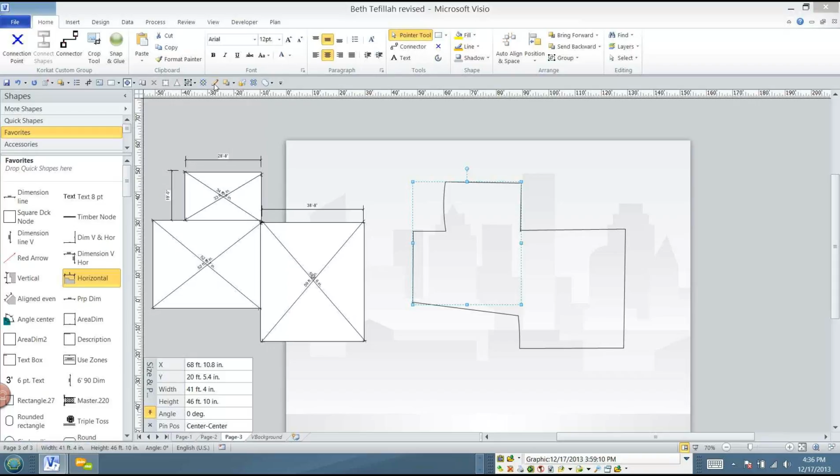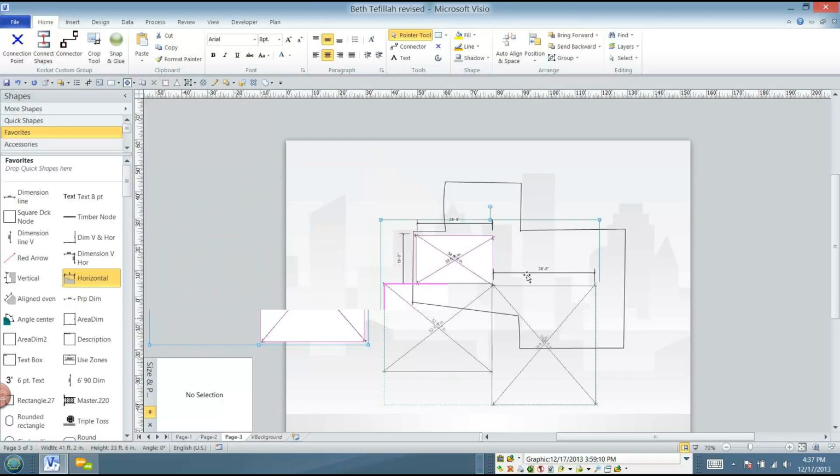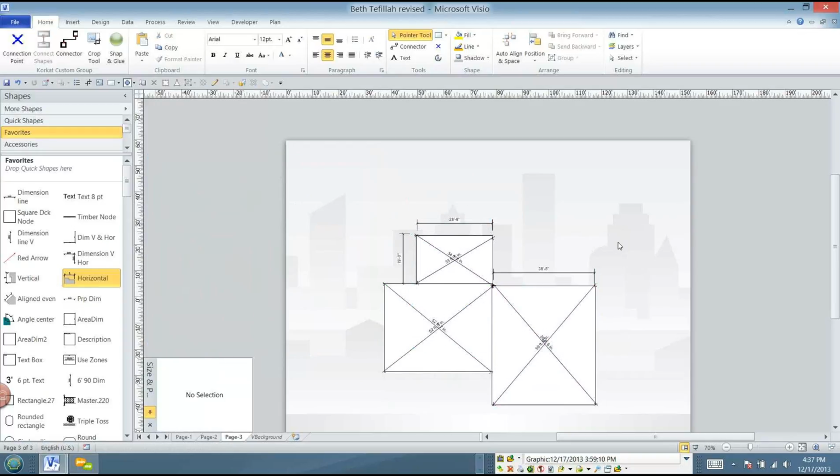This is in all likelihood what you would see. Be something similar to this. When you're walking out, taking your measurements, try to cut that up into usable pieces. Okay. So here you got a rectangle, here you got a rectangle. This is supposed to be a rectangle over here. But try to carve these up into rectangles, and it'll be much easier for you to get your measurements from. And it'll be a whole lot easier to convey to a customer how everything is going to fit together too. Right.